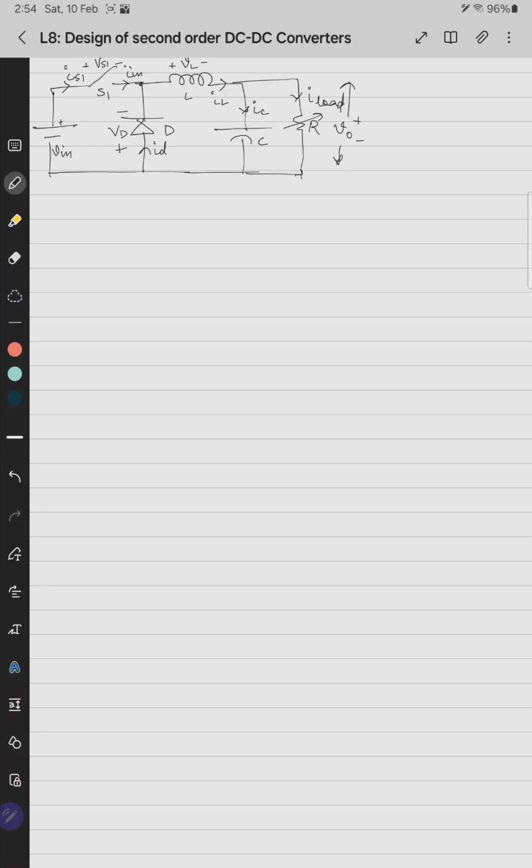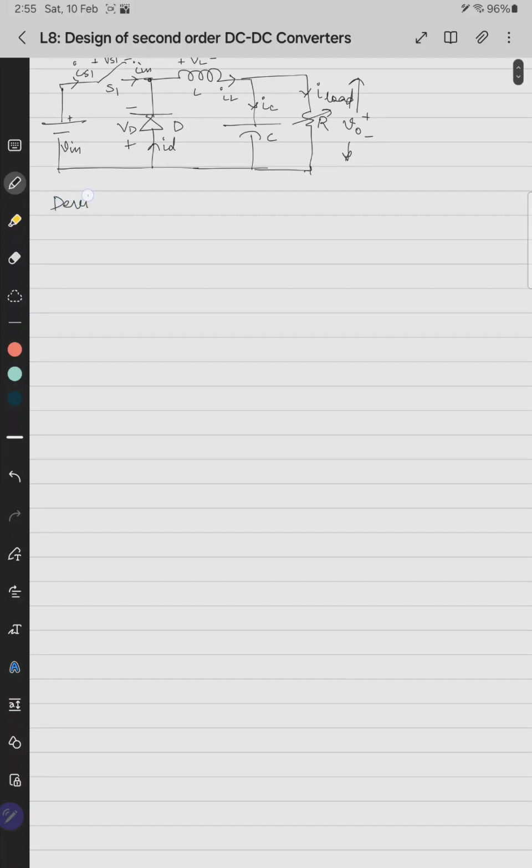And also we have to see the maximum current which flows through the device. As you know, a load is sitting at the output of a buck converter, so the current will be mostly governed by the load current. So that's why we have to see how to select the different power components based on the steady state and transient conditions. So here I'll write device, voltage, current, percentage voltage and percentage current rating.